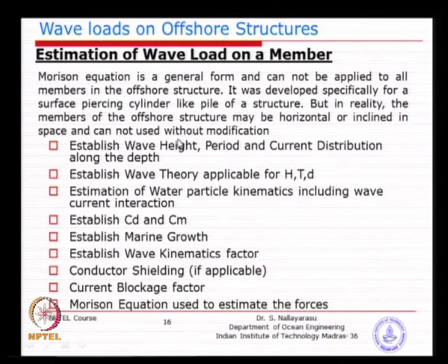The first one is to collect data on the wave height, wave period and the direction, and the associated wave theory for a given situation. Basically, we learned a little bit about the linear wave theory and the nonlinear wave theory, and where it is applicable, and which assumptions are violated if you select a wrong wave theory. So, basically we want to see how we select a wave theory, and then using a particular